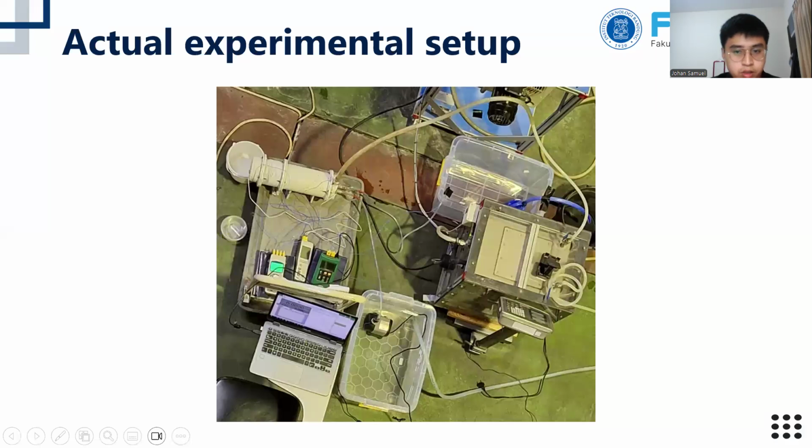And the heat loss to the surroundings with a temperature of 20 degrees Celsius is no more than 70 watts. So it is small enough to be neglected, since the heat transfer to the cooling water is about 1800 watts.